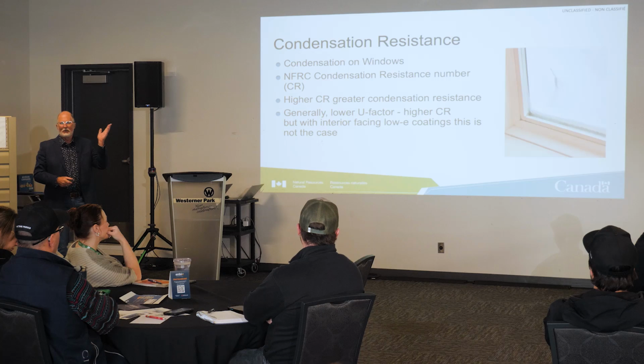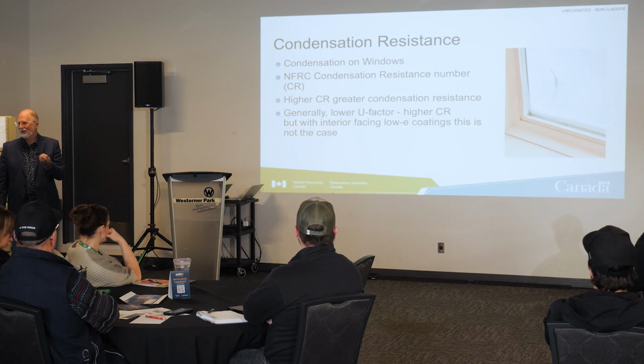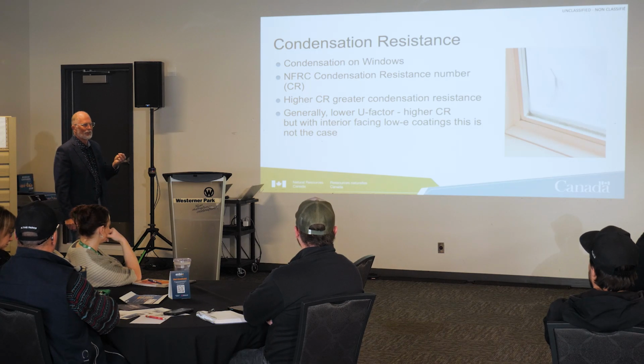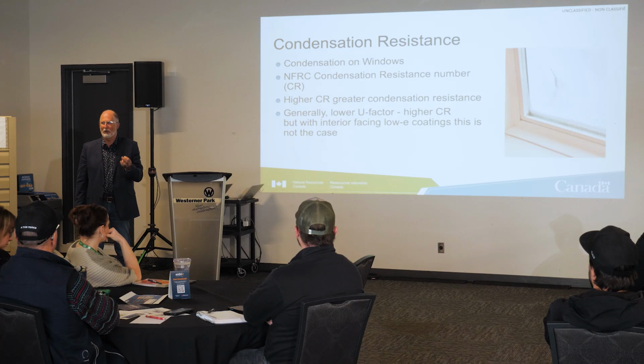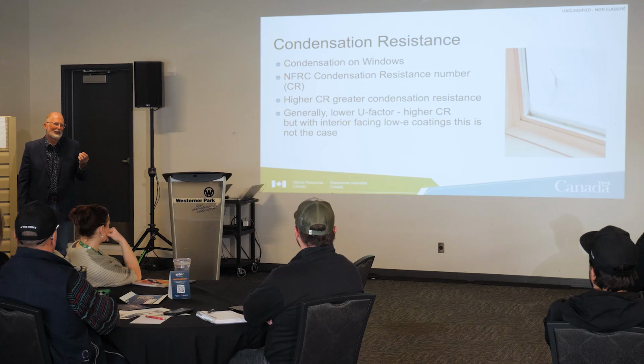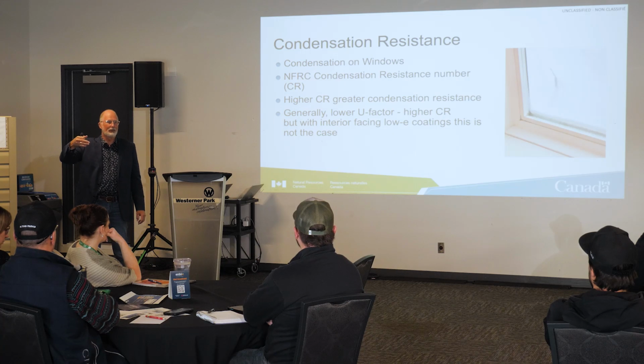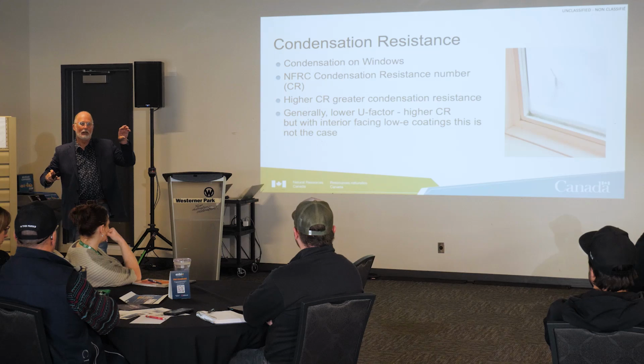The other thing that's interesting is, when you go through the first winter, what's the complaint that your homeowners often have? It's condensation on windows. In fact, it's probably not even condensation. It's probably more frost on windows, right? What's the difference between condensation and frost? One's a solid, one's a liquid, right? Really, it's the temperature of the surface. If you've got condensation on the window, that surface of the window is above freezing. If you got frost on the window, that surface of the window is below freezing, right? And the vapor in the air either goes straight to a liquid or straight to a solid. But it can convert backwards the same way.